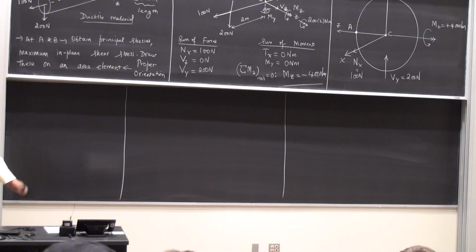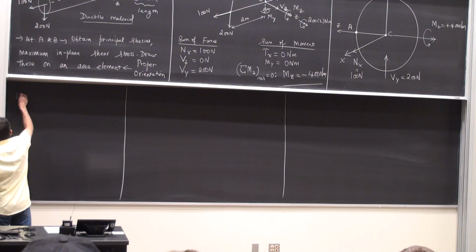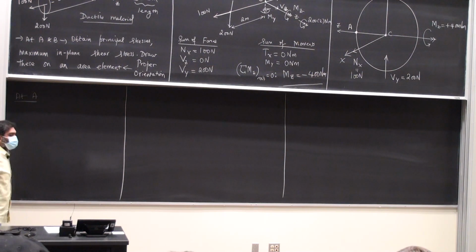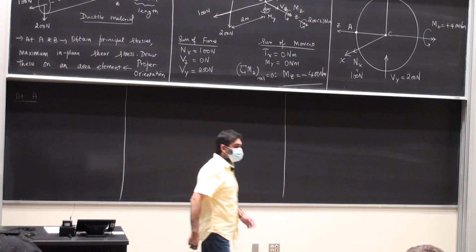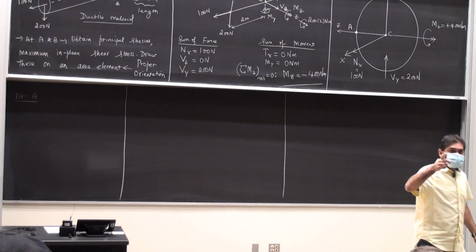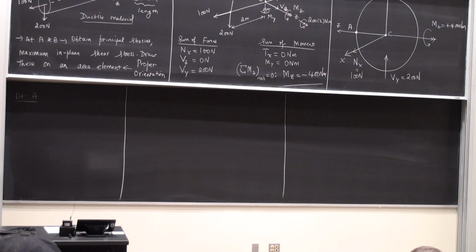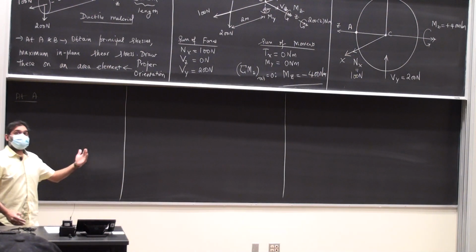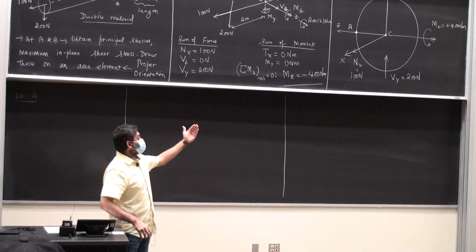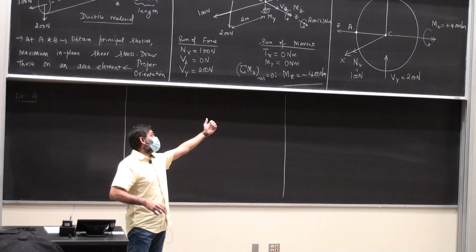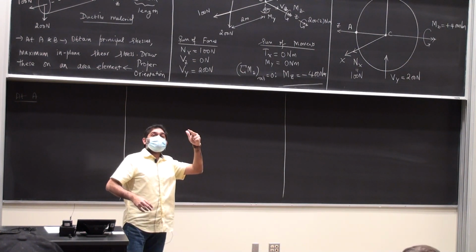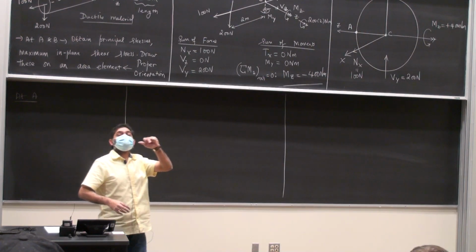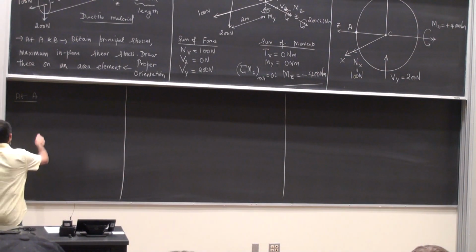At the point A, let's start off with point A. What are all the stresses? Okay. Is everything okay? At the point A, what are the stresses? I'm going to have a normal stress due to the normal force. So I'm going to have sigma xx. It's the xx direction, right? The subscript for the normal stress at the point A is xx because the normal force is along the x-axis. The subscript for normal stresses will be the same in both the indices. Okay? So sigma xx